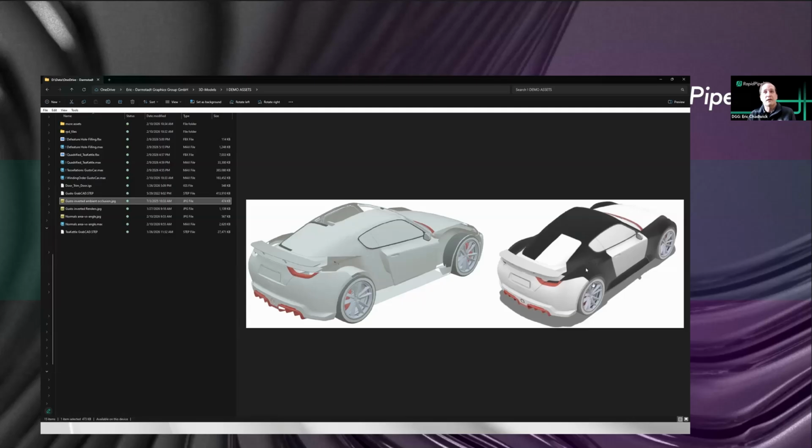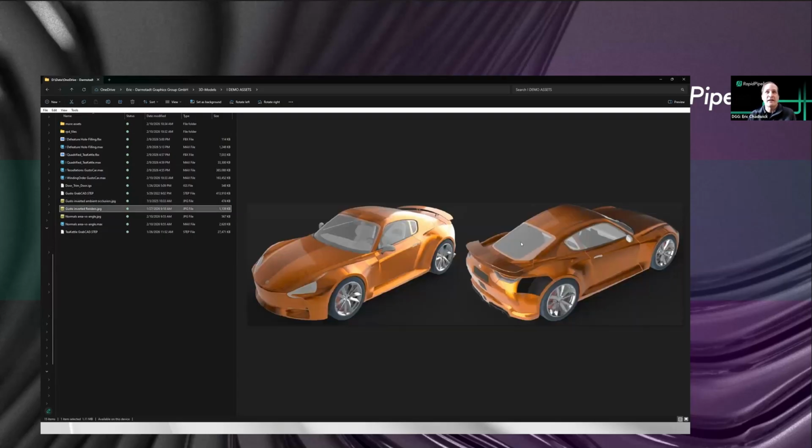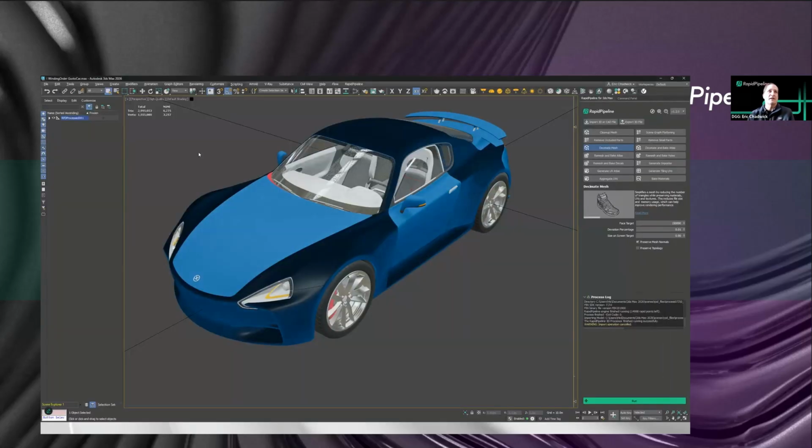Because basically, ambient occlusion looks at the surface and says, hey, are there other crevices here that are going to be shaded? Go ahead and shade those. But these things are inverted, so they're going to go black in the ambient occlusion bake. And so we have a tool that automatically fixes this model and makes it all look correct. And here you can even see, I think this is in the Substance 3D viewer, even though the patches are rendered double-sided, you still get these weird shading errors across the model. So it's something you really need to fix.